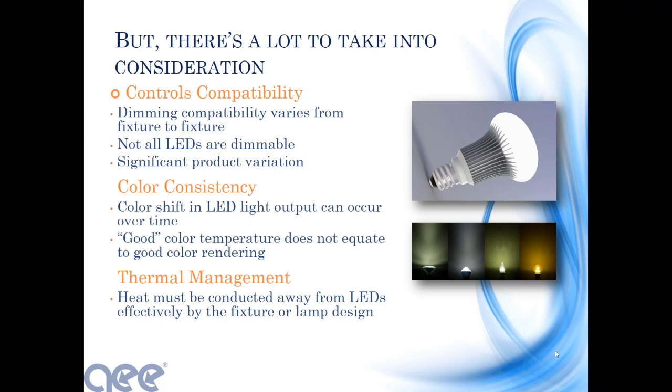So that's why the CFLs kind of got a bit of a bad name when they came out to market, because they got nowhere close to the life that they were talking about on the screw-in side. Same thing on the LEDs. If you're putting it into the lamp on your nightstand, great, no problem. It's going to be dissipating heat, so it'll last forever. Okay, going into a can, you're going to have that same issue where you are going to have some temperature, thermal management type of issues.